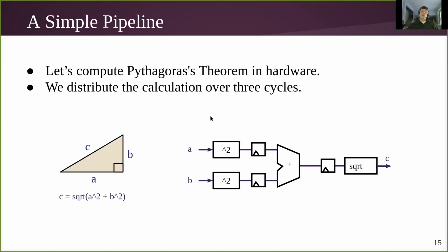Okay, so now that you've played around with some simple things inside Makerchip, I'll introduce the first new concept in the language, which is pipelines. Pipelines is typically a concept that you learn later in the logic design curriculum. In transaction level Verilog, pipelines are a very fundamental notion.